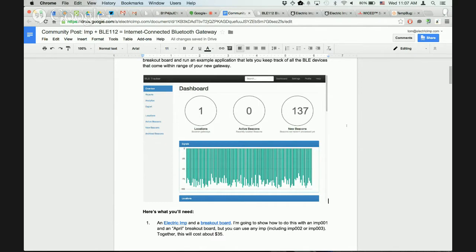Does the device kind of act like an agent for the BLE device? So the BLE device has some stock code, it knows how to handle certain commands, and then your device sends commands to it over UART to get it to do those things? Yeah, that's about right. You're treating this BLE 112 module like a normal peripheral, like you would a sensor or something like that, that you could just send a known set of commands to. Cool. It's a pretty powerful peripheral that way, right? But that's the way that it works.